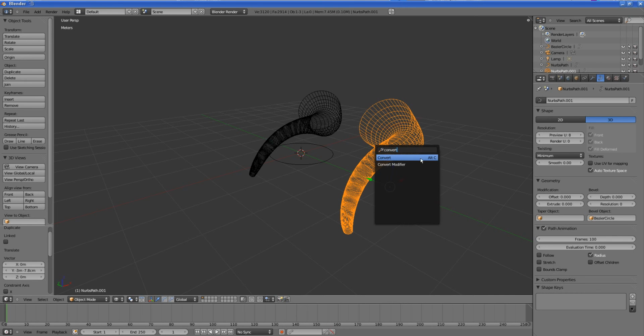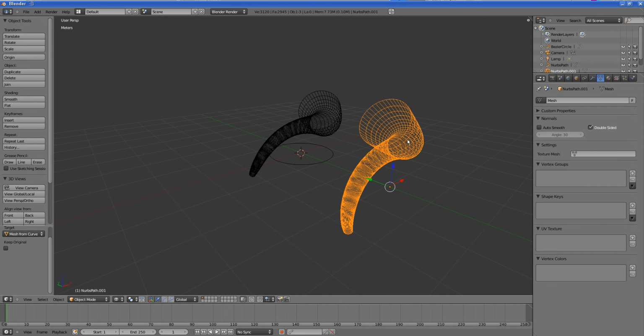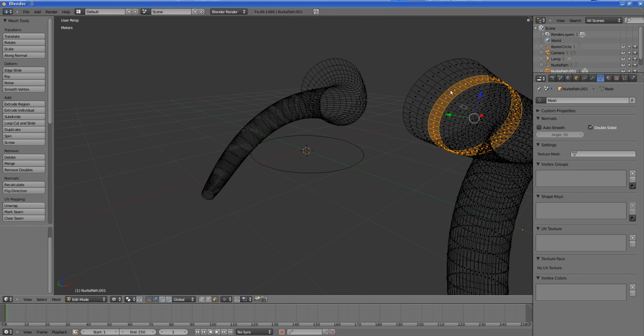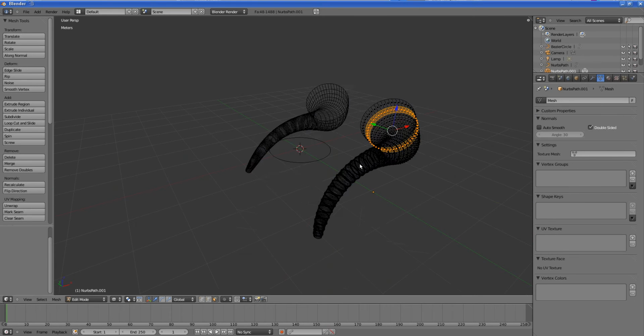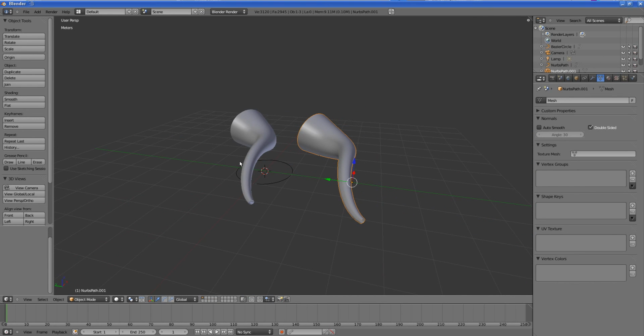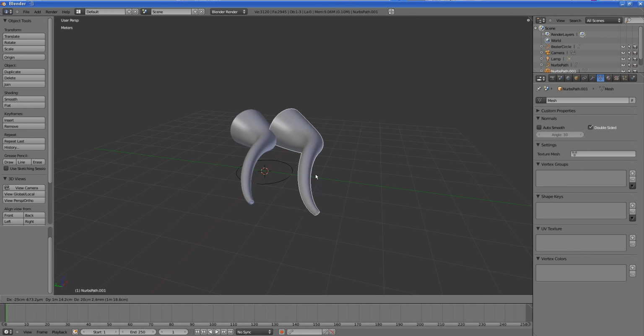and you have this convert operator. The hotkey is Alt C. So now we want a mesh from a curve. We have a curve object, we need a mesh from it. So choose this. Now you'll notice that we have a mesh object because the object data turns into the mesh properties. I can tab into the edit mode and you have access to the individual faces. Cool. That's how you can start with a curve, create a shape and then convert it into a mesh. Let's move it in the y-axis.